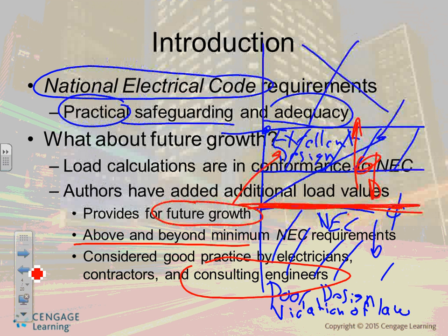So we try to push a pipe per equipment, mechanical equipment. What we do is when you come out of that panel, typically we go 3/4 of an inch out of that panel on the top, and you send, remember those 8 conductors that we did the calculation for? So you come up with 8 conductors, which give you 6 circuits, 6 20-amp circuits coming out of this pipe.